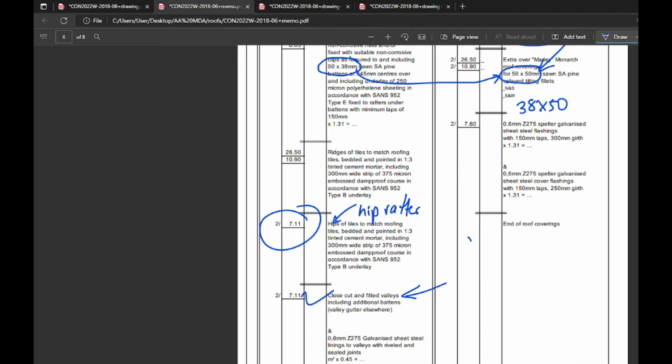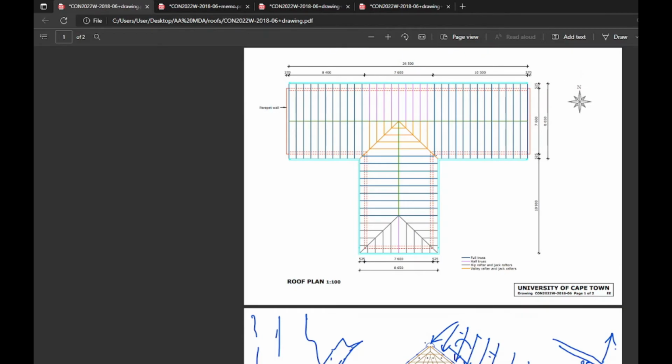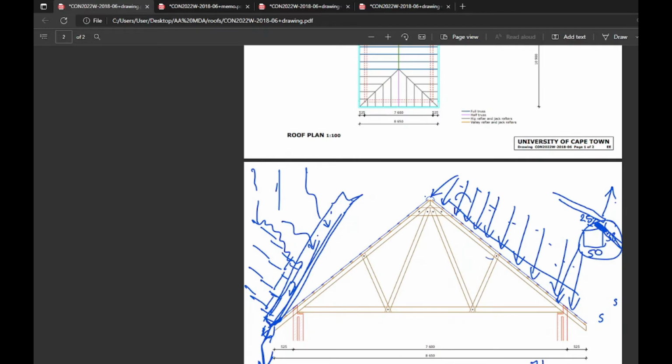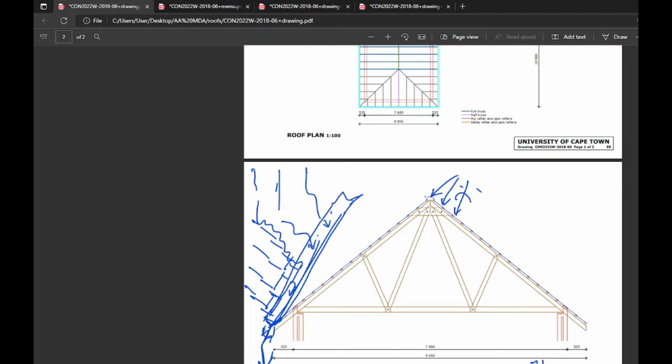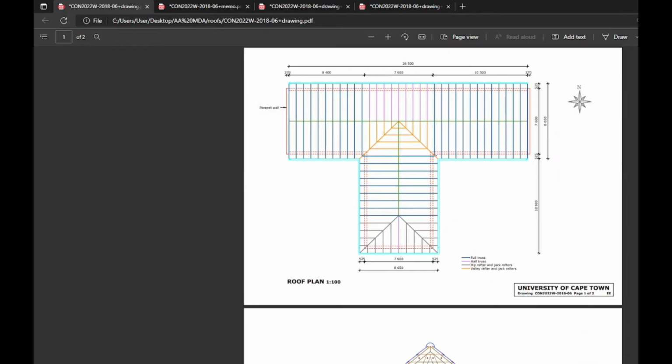Let's go up. Okay. Flashings apply where we have roofing meeting brickwork. All right. That is typically gable end. I need to correct myself. Not necessarily just a gable end. It is a gable end with a parapet wall, because you can have a gable end with a barge board, and in that case you would not have flashing, right? Right or wrong? Correct me if I'm wrong.